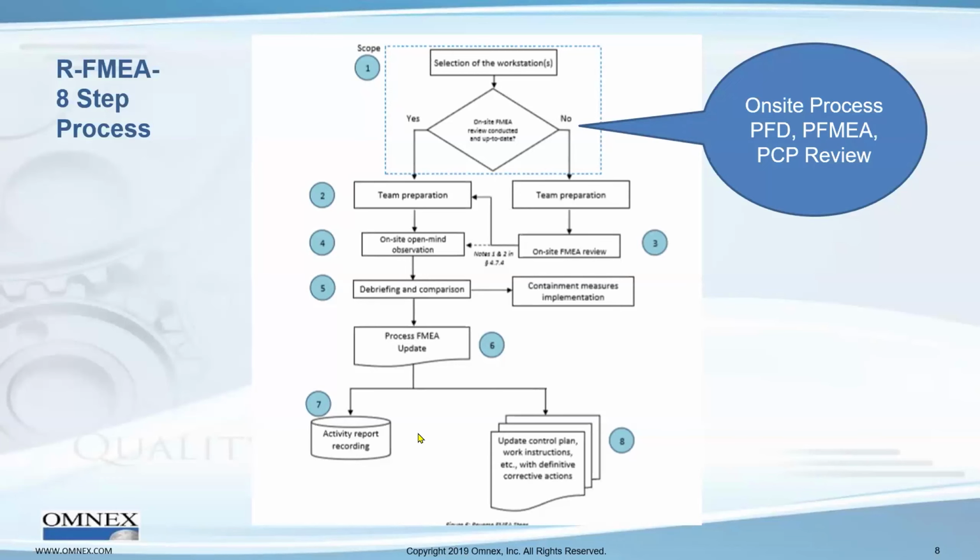And so the team would then get prepared. Prior to going and doing the reverse FMEA, we would review the PFMEA for Op 30, and we'd make sure that the flow chart was appropriate, that the format and the information was substantive in the PFMEA, and that we had a good control plan that covered the detection processes in the operation we're focused on.